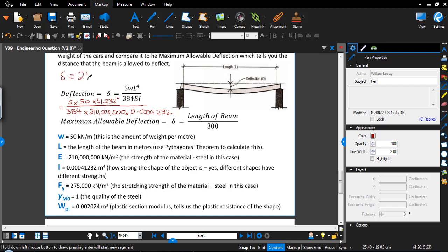So this is the deflection. It's 21 point, I did have to double check, I'm going to round up. So this is meters. Usually you'd expect something like this in centimeters. This is massive, gigantic. Imagine that this came down 21 meters. This beam was way, way, way too small. This is a definite fail.